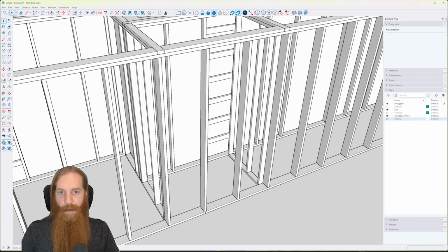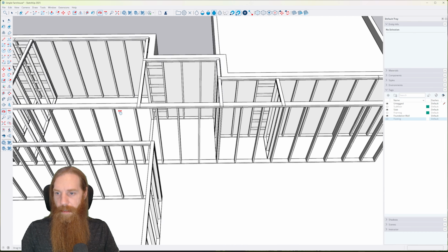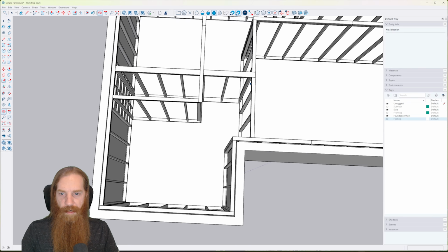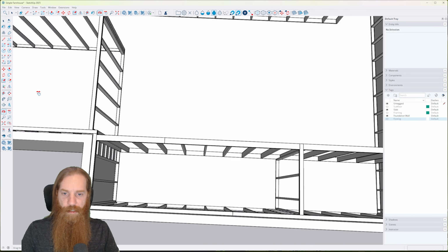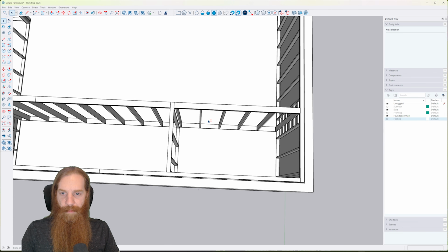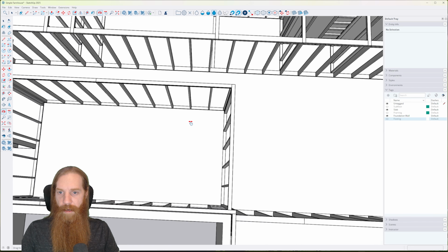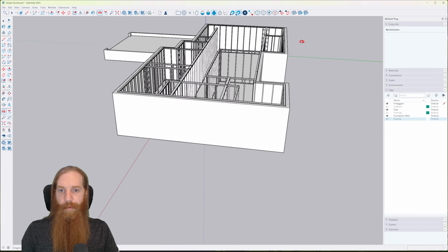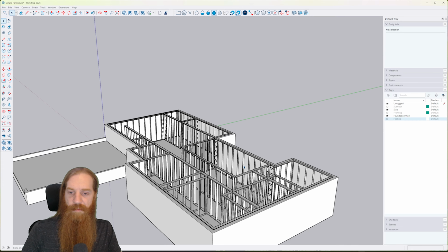Okay. There we go. I think we're done. I'll look for any additional seams I may have missed in the plates. Make sure they all land on studs. They're real easy to spot because you just look for a line on your plates. Since all the lines should be hidden underneath a stud, you shouldn't see any others. So we look good. As you can see, I got all of the framing, all the studs at least, in at this point.